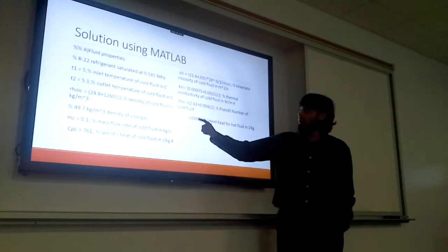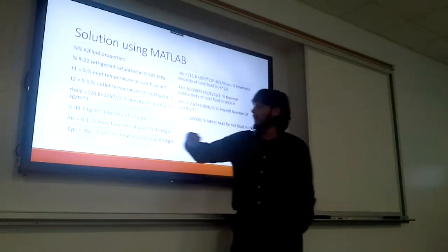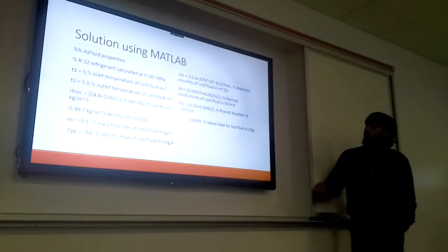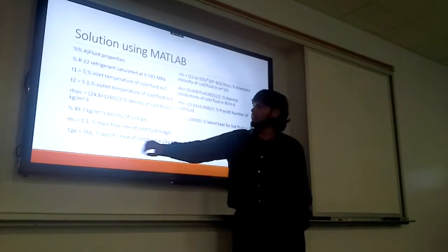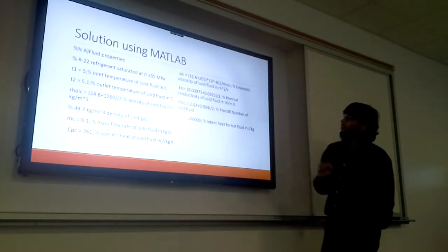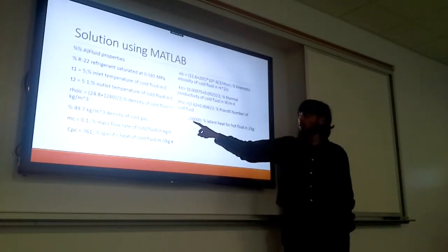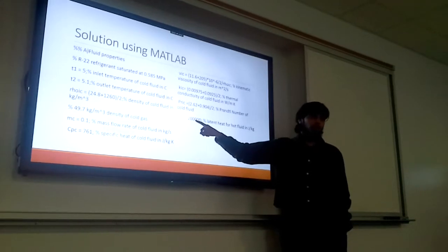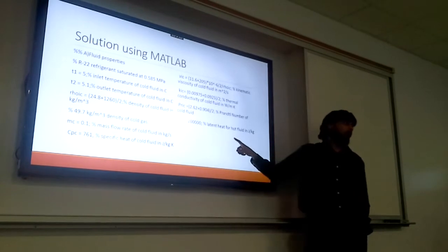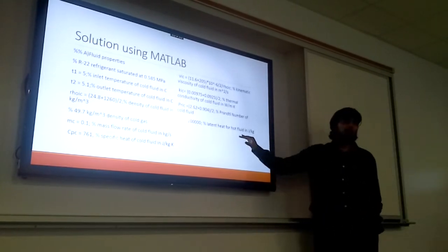And also, that's the information that was given. I also put the mass flow rate and the heat capacity as well. I think that should be an average, but nonetheless, that's still a number you can use. The viscosity, I also took an average of that, and also thermal conductivity. So I took the average of all those. And obviously the most important one, the 200 kilojoules per kilogram, the heat of vaporization or enthalpy of vaporization, I also noted here. It's part of the properties. And I put it as latent heat for the hot fluid.